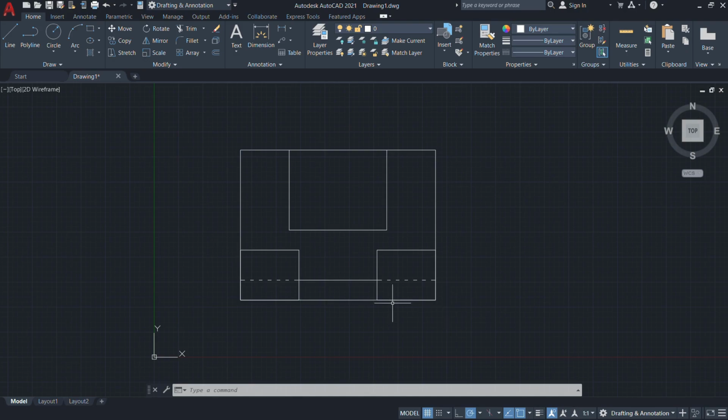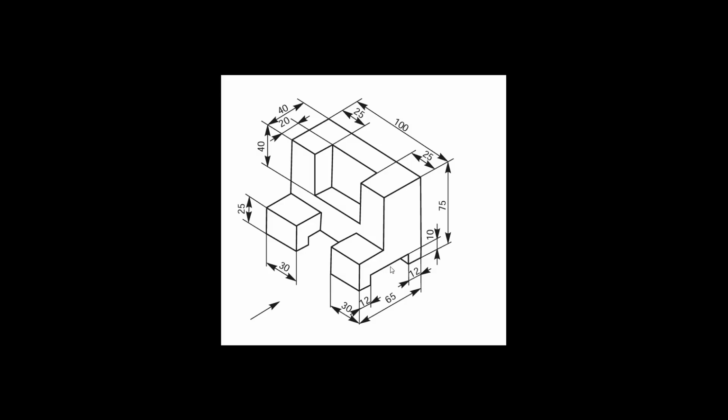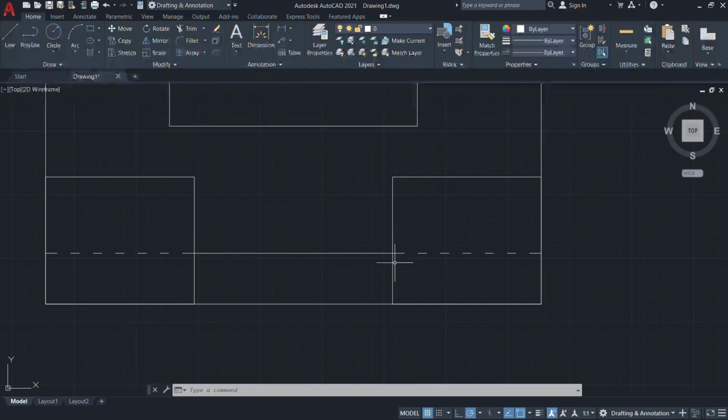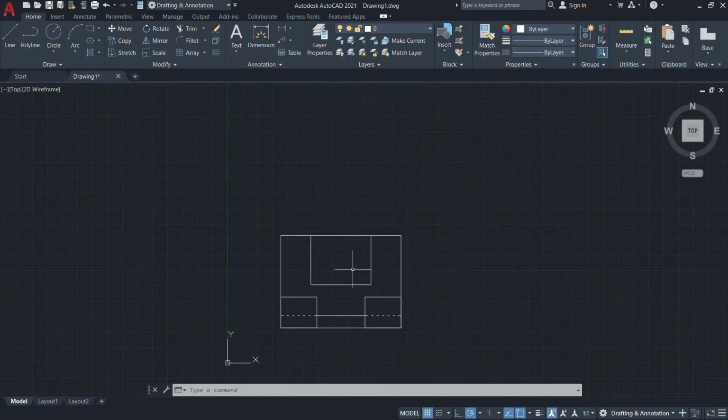Now the front view is clearly drawn. The visible edges are just to look like the outer portions. The non-visible areas, that is the hidden lines, are just to represent this particular pocket portion. Look at that, from the rectangular front end section, we cannot see these edges itself. That's why they are replicated as non-visible areas, hidden lines.